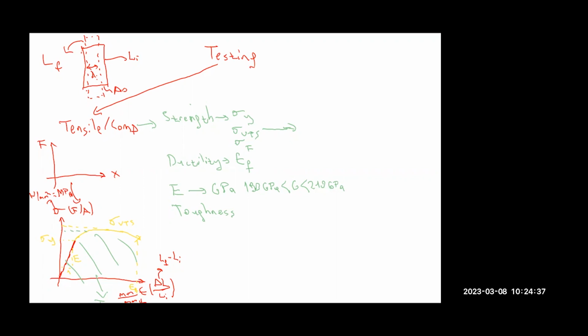And when I say dislocation, that means they are the carriers of plastic deformation. That means without any dislocation, we don't have any plastic deformation. Okay. So we will mainly investigate this plastic region and the different strengthening mechanisms, and we'll try to answer the question of how can we enhance the strength of a material.